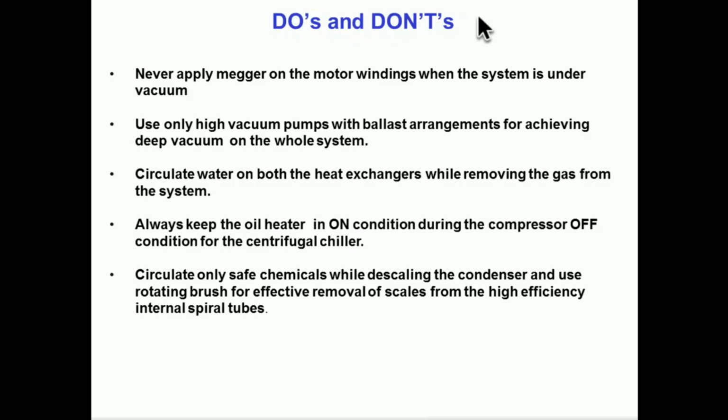Always keep the oil heater on. The higher the oil temperature, the lower the absorption capacity of oil from the refrigerant. That is why we always keep the oil heater on, especially on chillers, even when the chiller is not running. Otherwise this can lead to unnecessary oil carryover in the system.